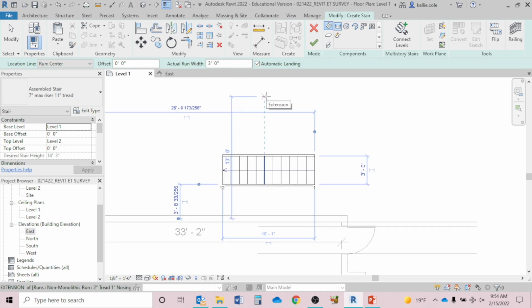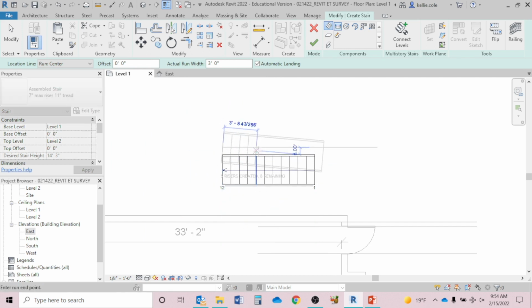Where you place the cursor again matters because I'm drawing the center of the stair, right? So if I accidentally have a cursor too close to the stair, it builds it crashing into it. I hit escape. So I'll pull this up, maybe if that's the center there, I'll pull this up like 4 or 5 feet more. Again, this method is place the stair in, fix the dimensions later.